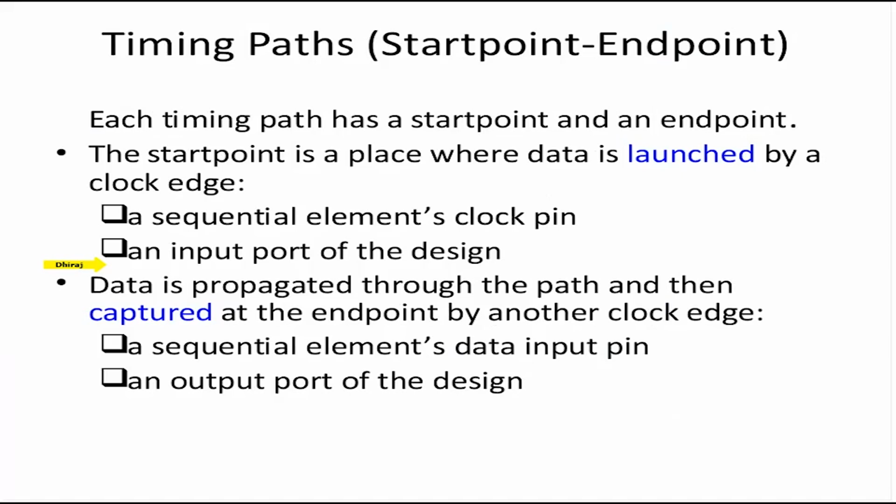So if hold timing fails, there is nothing we can do. The chip fails, the design fails. Hold timing paths depend a lot on the clock tree after the physical design is done. Since Design Compiler does not have any information about the clock tree, it does not fix hold unless we tell it explicitly to do so.